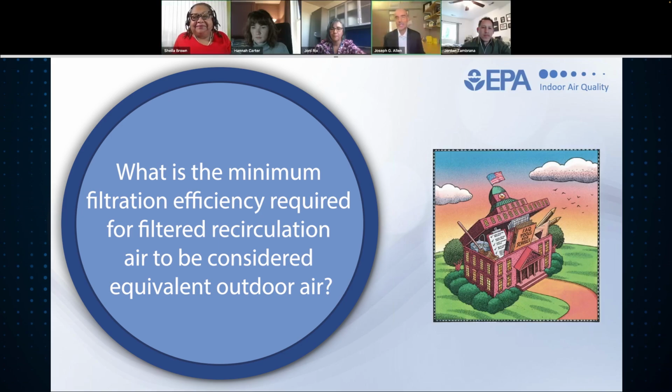Between ventilation and filtration, I liked what Jordan said, right? You want to get the maximum grade filter that your system can handle. Most systems can handle MERV 13, especially the low pressure drop MERV 13 filters. There's a push in some corners to say, hey, we can close off outdoor air ventilation and just clean the air over and over inside. I think that's a little naive, to be honest, in terms of what we know about the science of what keeps us healthy and functioning well.